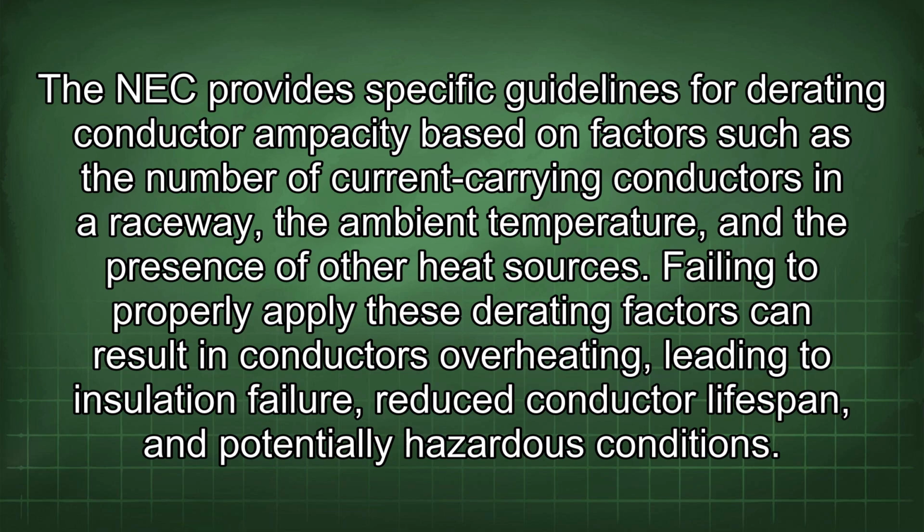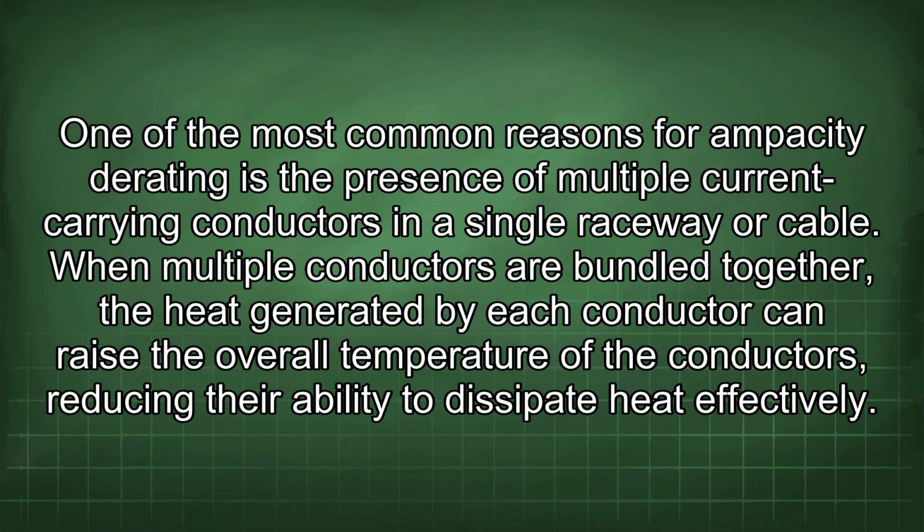potentially hazardous conditions. One of the most common reasons for ampacity derating is the presence of multiple current-carrying conductors in a single raceway or cable. When multiple conductors are bundled together, the heat generated by each conductor can raise the overall temperature of the conductors, reducing their ability to dissipate heat effectively.